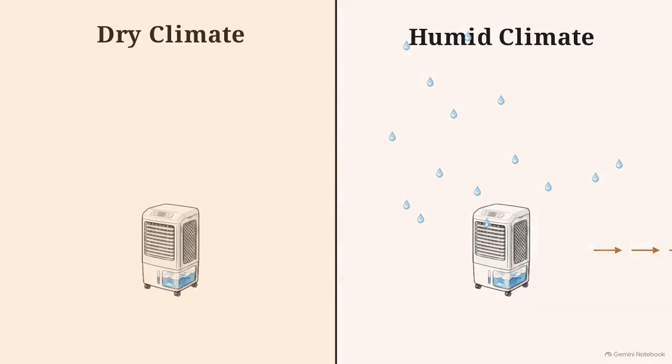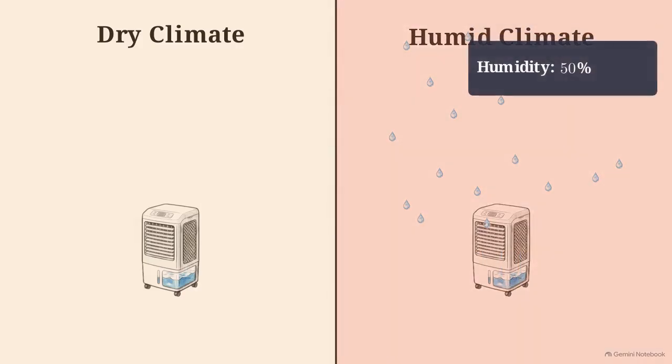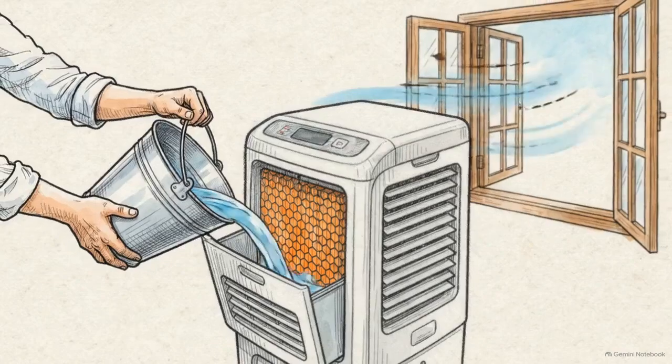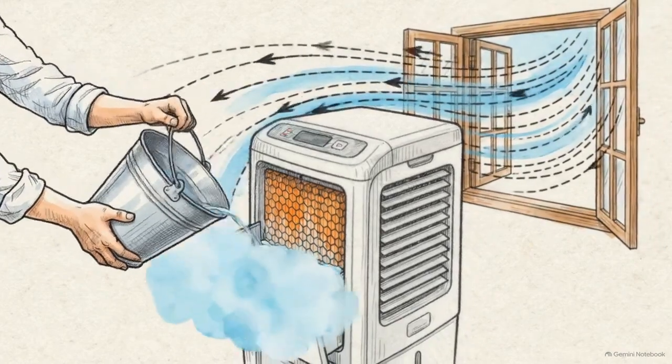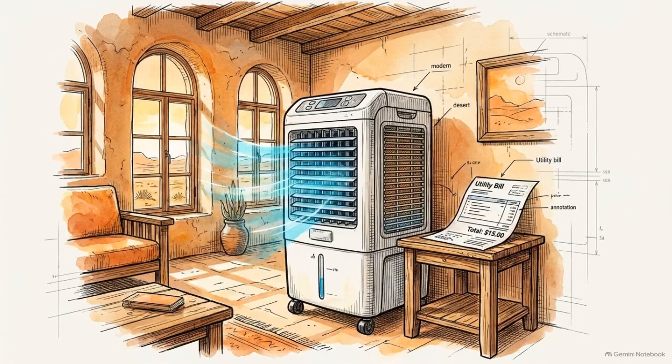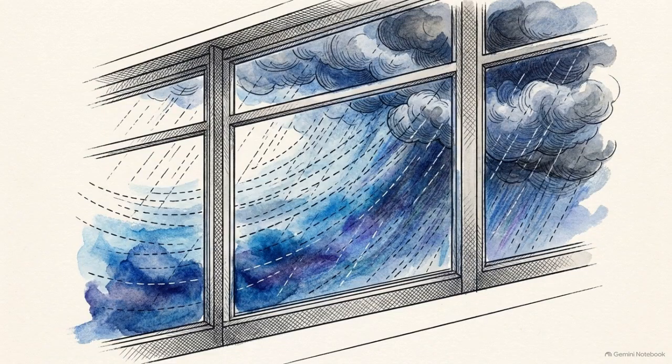If run in a humid city, the room rapidly transforms into a damp, sticky space. To keep the system running effectively, the homeowner must constantly refill the water reservoir and leave windows open to ensure strict cross-ventilation. When matched with a dry climate, an air cooler is a highly efficient financial asset, but it is entirely at the mercy of the outside weather.